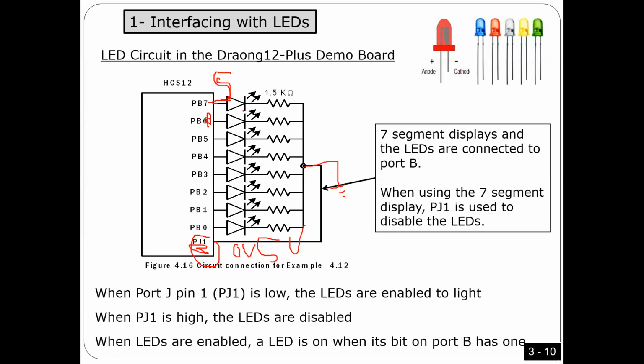So I want to make it flashing. Remember, every LED should have one bit in a byte. Bit set to turn it on. Bit clear to turn it off. That's it. But when I turn it on, I'm going to wait some time because I want to make it flashing.